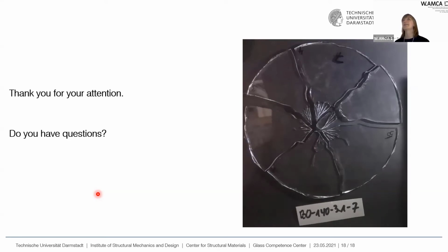So you're asking if there are cracks before the experiments in those glasses? Induced by the experiment, so small that I haven't seen. Okay, so micro cracks induced by the experiments, but so small that I cannot see them. I guess that's the case, because for subcritical crack growth you need this crack tip, which then grows after a couple of hours, days, weeks, whatever the time period is.